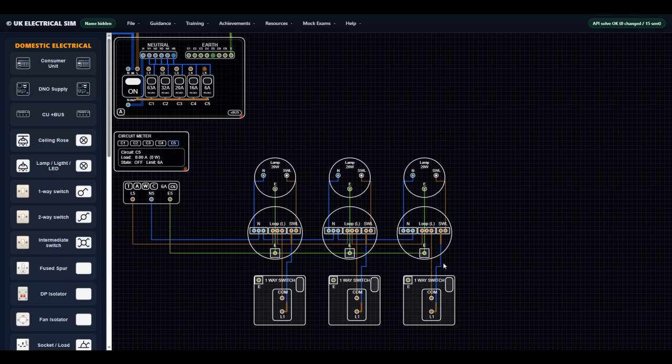We have mentioned colored sleeving before, but now let's show you how to add or remove it. To do that, simply highlight a wire, then hold down Alt on your keyboard and press the letter B. This will toggle the sleeve color between brown, blue, or no sleeving. We can now finish connecting the remaining earth wires, linking E to E across all components.